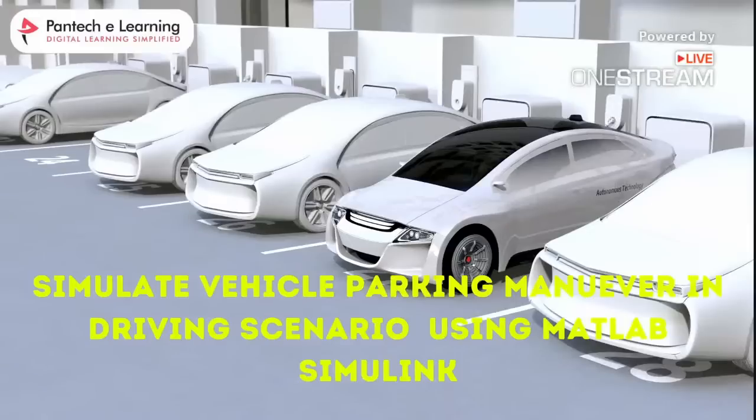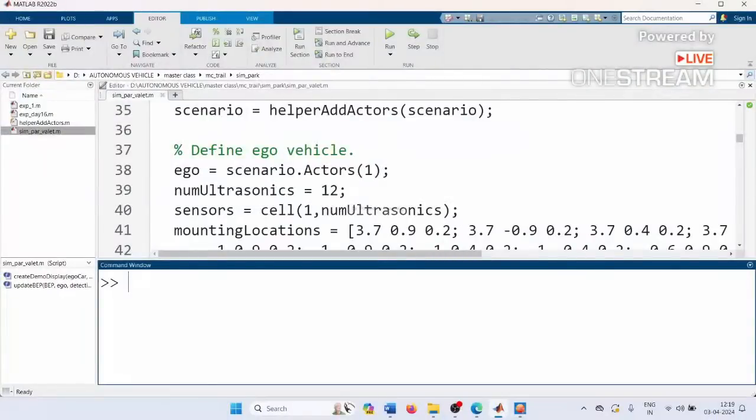I'm going to open the MATLAB software here. So in this example, you have to simulate an ego vehicle. It has 12 ultrasonic sensors. This sensor has a maximum range of 5.5 meters, the horizontal field of view is 60 degrees, and the elevation field of view is 35 degrees. So I am going to give the information through this MATLAB command window.